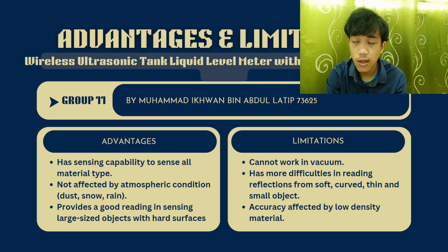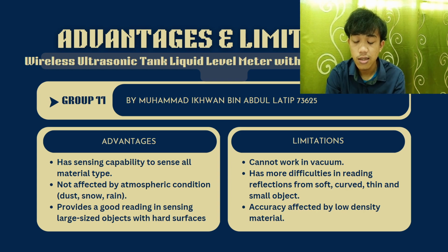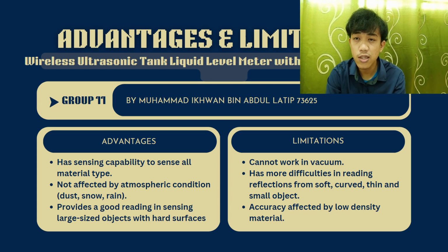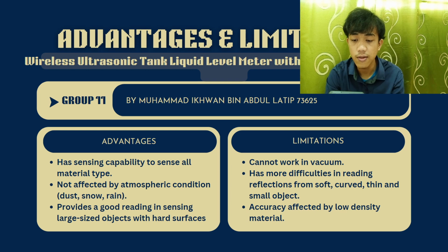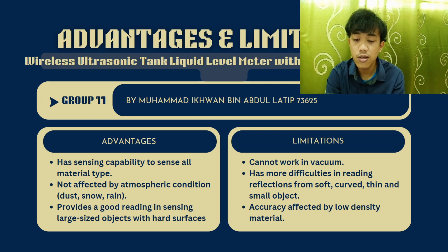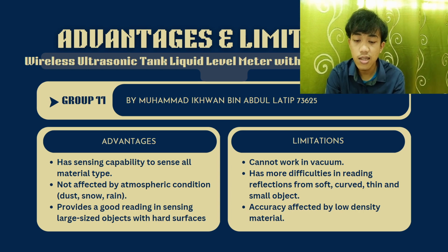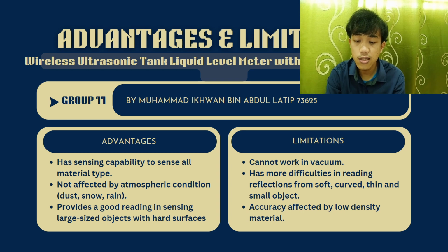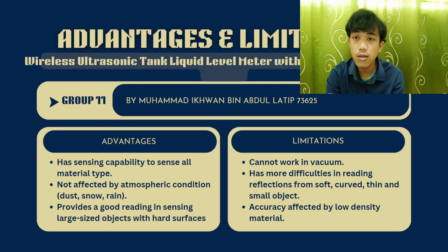In contrast, the limitations for this sensor are that it cannot work in a vacuum because it needs sound to travel to the sensor, and a vacuum does not have the medium for sound to travel. It also has more difficulty reading reflections of sound from soft, curved, thin and small objects because sound is absorbed by such materials. Its accuracy is also affected by low density material because low density material tends to absorb sound.